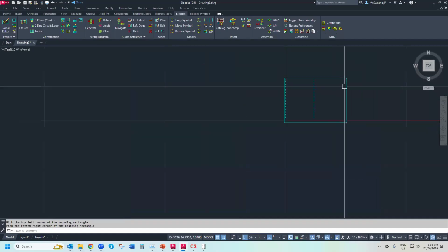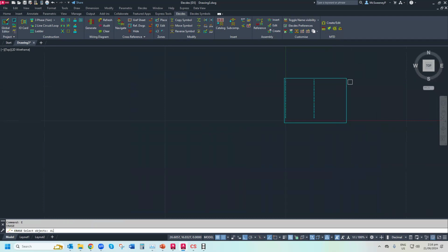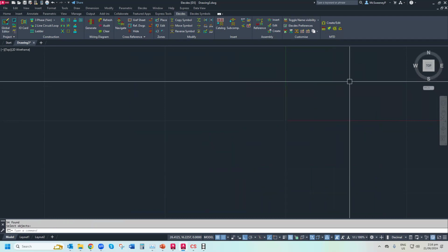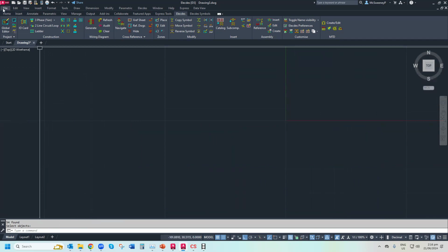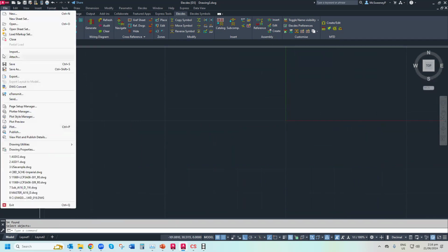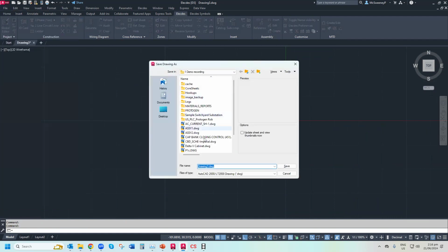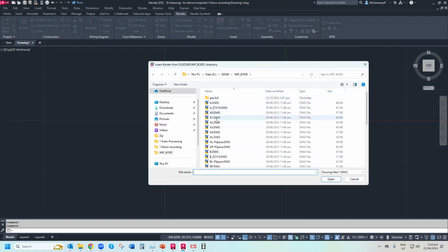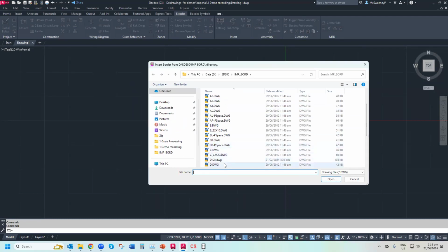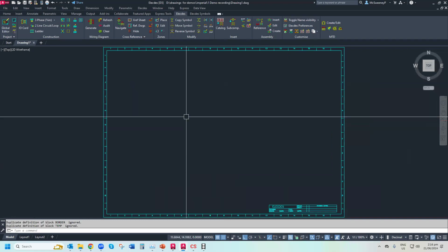All right, and erase. All right, so now I go into the drawing side of things. And for that, the first thing I want to do is to go File, Save As. And we're going to save this as drawing number 1. Now, I've saved it as drawing number 1, and now I'm going to go and put in a decent sized border, A1 or a D size in American speak. Okay, there's my D size border.